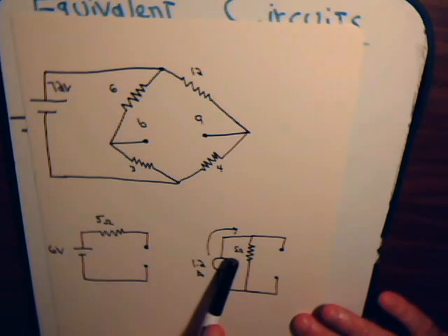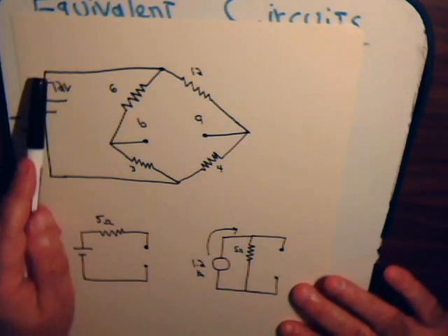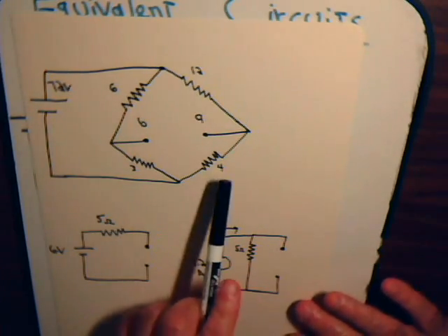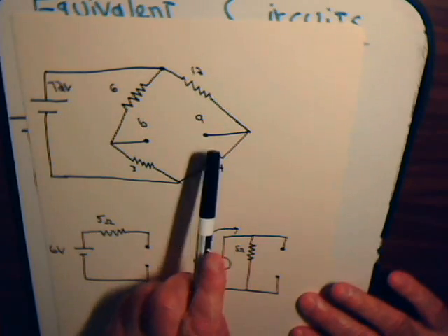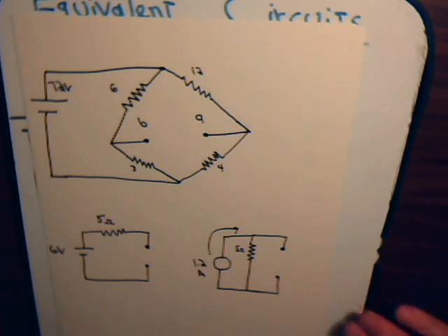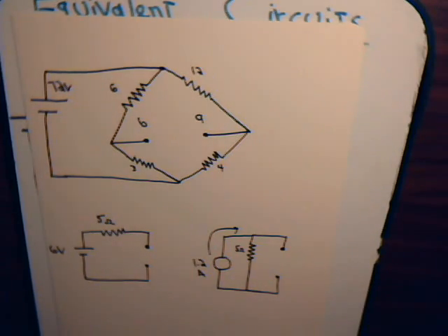Now, this 5 ohm resistor, you can call it the Thevenin resistance or the Norton resistance. It's the same in each case. And as you saw in our previous video, the way we determined that value was, as you do for any other circuit, remove any current sources or voltage sources. Here we just had a voltage source, so imagine drawing a line through this. Then for the remaining circuit, we determined the resistance as seen across the terminals AB, and that we determined to be 5 ohms.